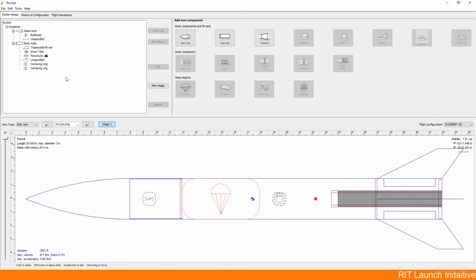You can also use this to override the mass of your rocket once you assemble it. Keep in mind that the sustainer mass does also include the mass of the motor. If you want to modify it without the motor there, you can change to no motors.